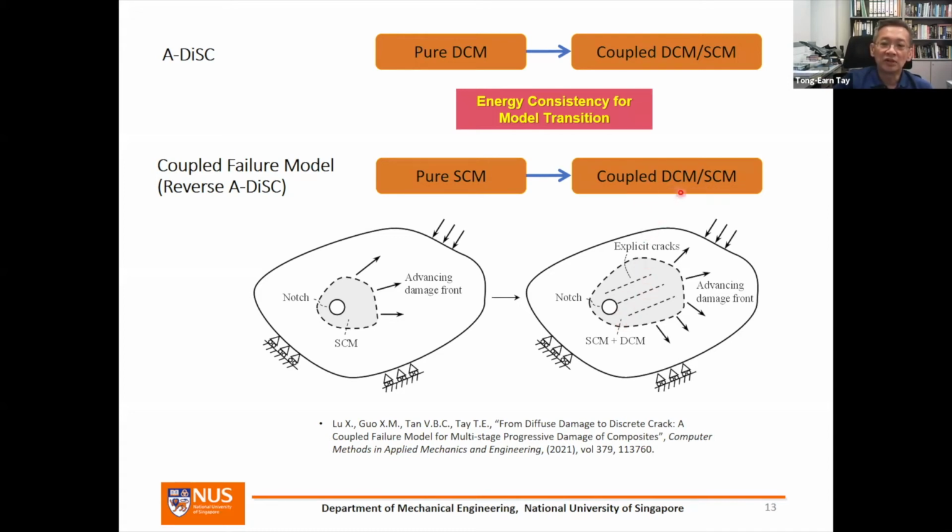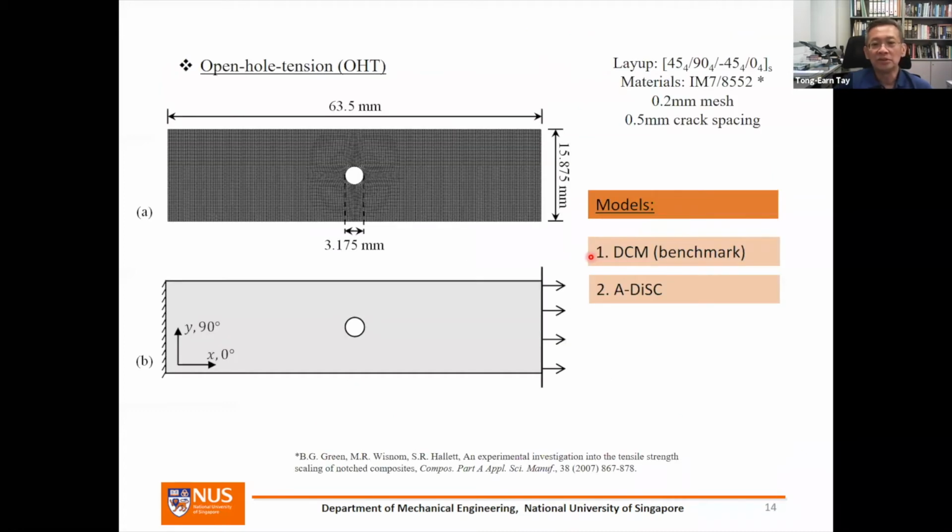That means some of the larger cracks are retained as discrete models as well, but the less active damage is converted or retained as smeared crack. That is also okay. And then my ex-student told me that this is more efficient than what I proposed previously.